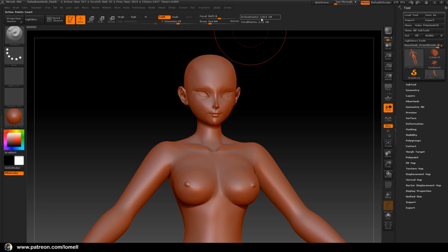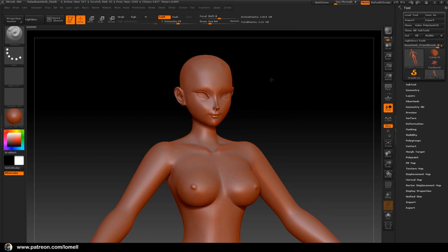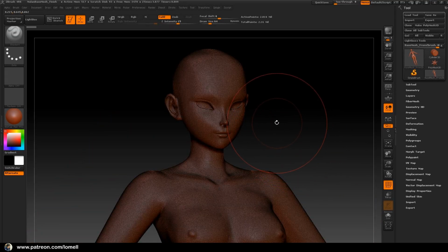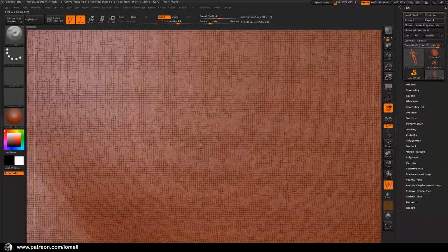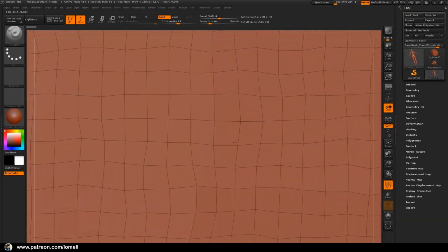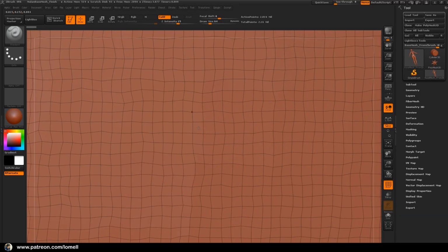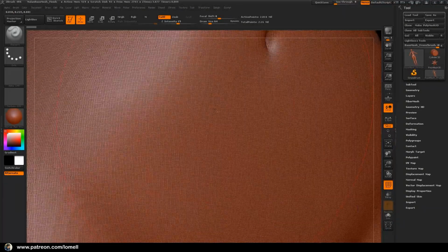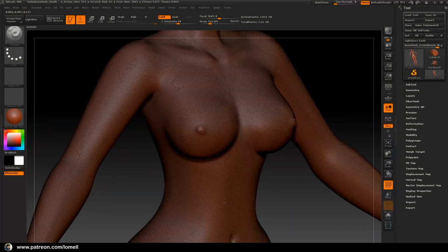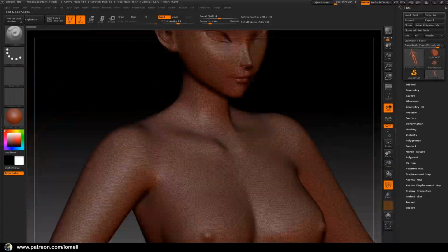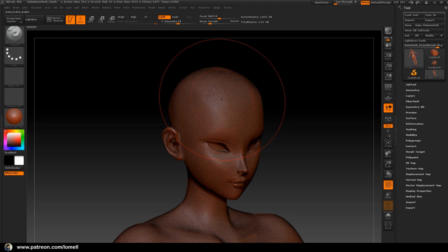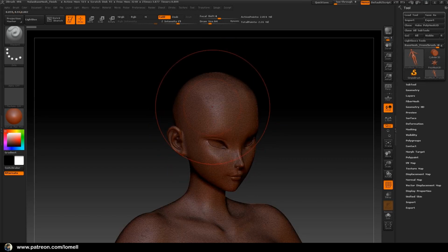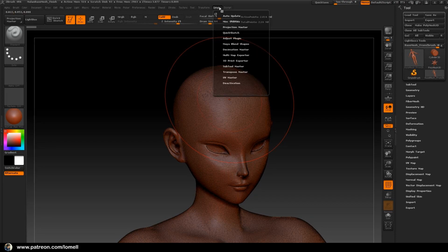This object currently has 2 million vertices. Just press Shift F on your keyboard and look at the surface of our character, and it has so many vertices in it, and 3D Studio Max cannot handle such numbers of points. So we have to reduce this one, because if we import it into 3D Studio Max right away, 3ds Max might crash. Okay, so to reduce this one, let's just go to Z plugin and drag this over here,